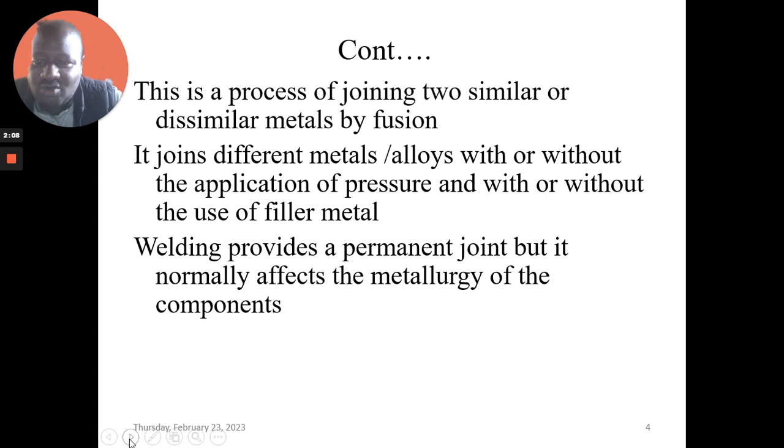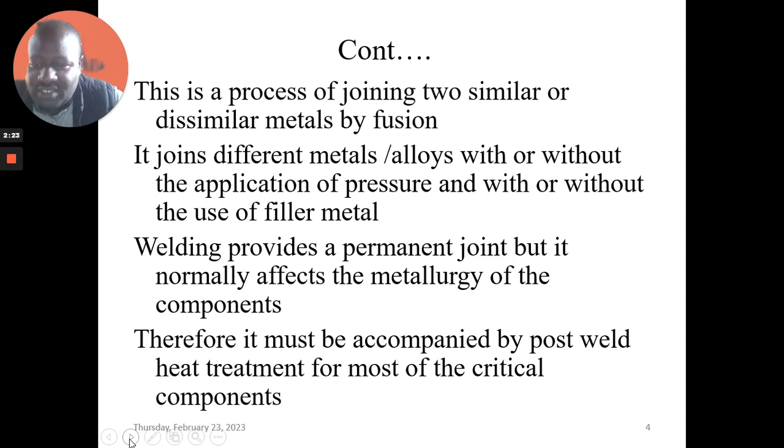Once the component has been subjected to heat, the metallurgy or the composition of that metal is being affected. So therefore, it must be accompanied by post-welding heat treatment for most of the critical components in order to bring back the metallurgy of that workpiece.